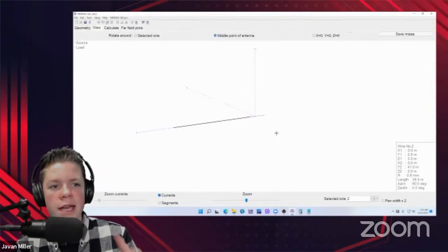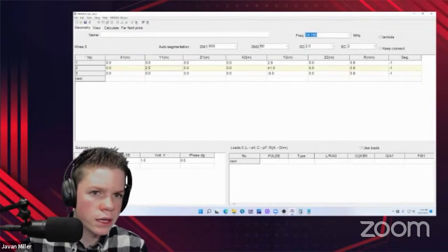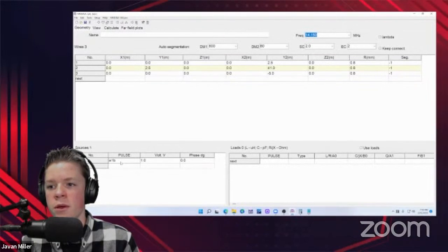Oh yeah, so when I added the second wire there, it kind of threw off my source, or my feed point. So I'm going to change that back. Does that inductor go to the end? Is it towards the end of the coil, or is it closer to the beginning of the feed point? The inductor is going to be close to the feed point.